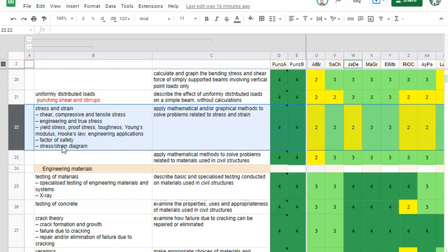Why? Because we don't know the exact forces. That person might think that they're 100 kilograms, but they're really not. We think we understand the metal, but we really don't. We don't know every atom that goes into the metal. We're using imperfect understandings of inconsistent materials. So we make our best guesses and we add a factor of safety, right? We halve the amount of load that can be applied.